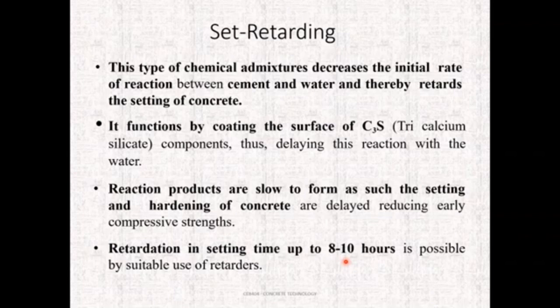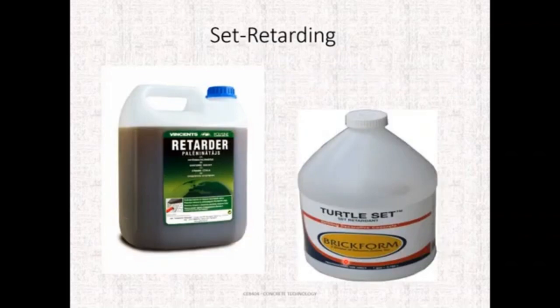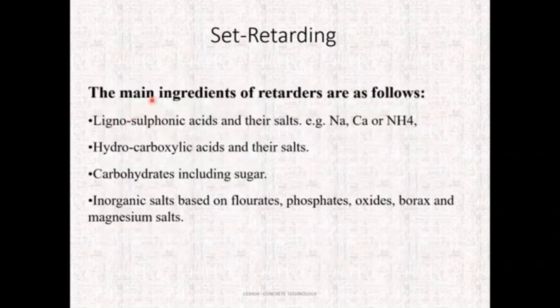In such scenarios, we can use retarders to delay the setting of the concrete. The common ingredients in retarders are lignosulfonic acid and their salts, hydroxycarboxylic acid, and carbohydrates including sugar.